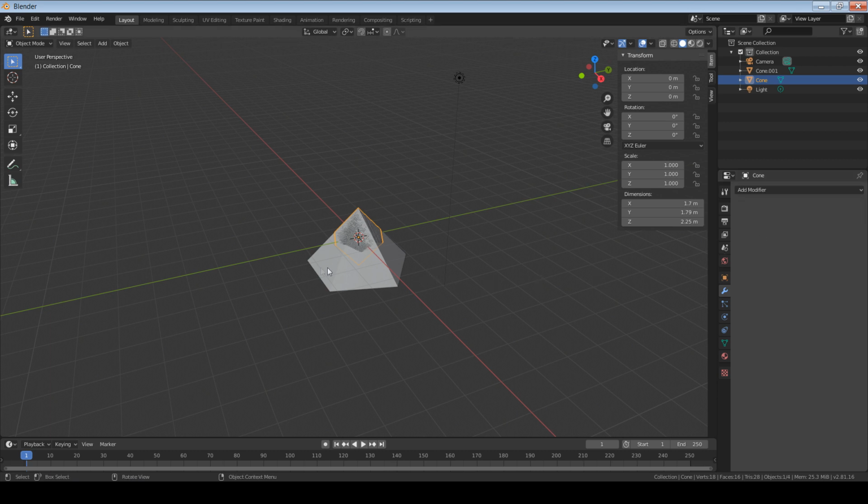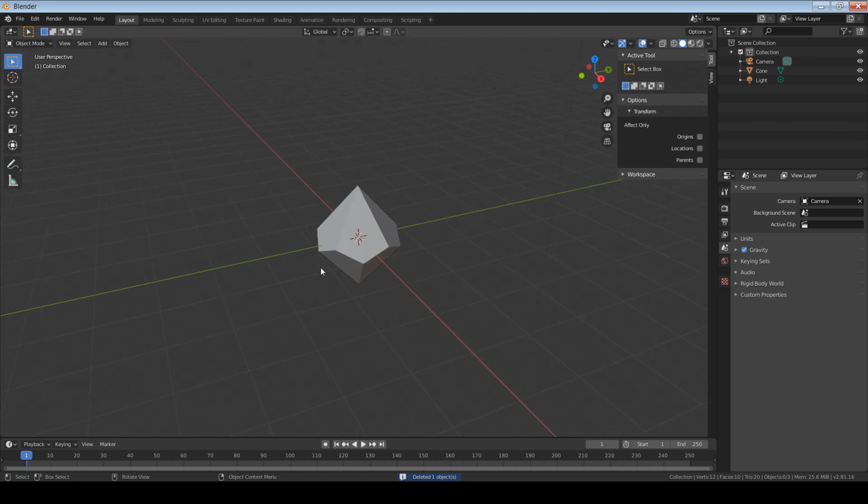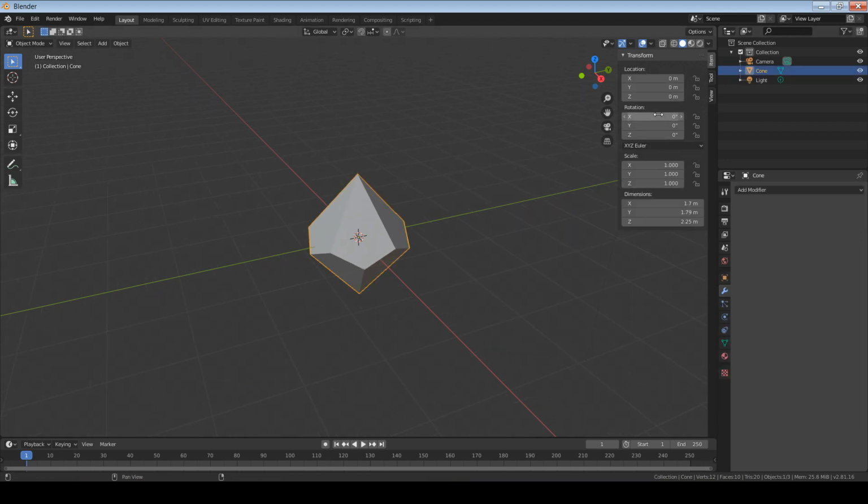Once you click Apply, you'll notice that one of the cones has pretty much disappeared while the other is still hanging around but looking a little funky. Once you select and delete the remaining complete cone, you'll now have your D10. And for the curious, the name of this shape is pentagonal trapezohedron. All we have left to do now is to reposition and resize this D10, so go ahead and rotate it by negative 54.3 degrees on X,